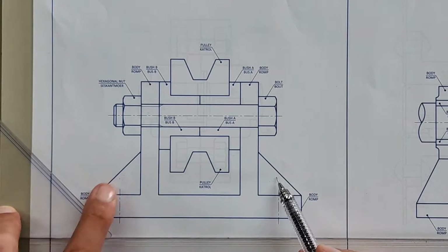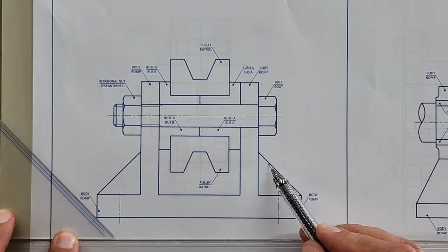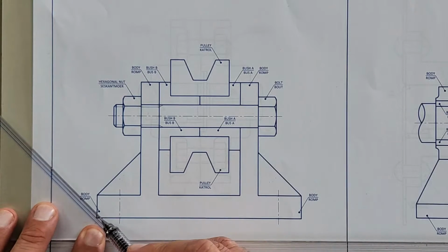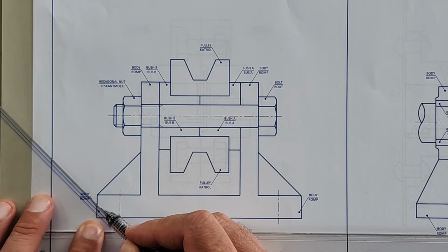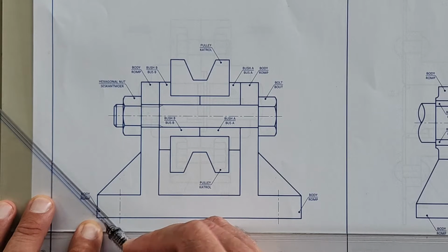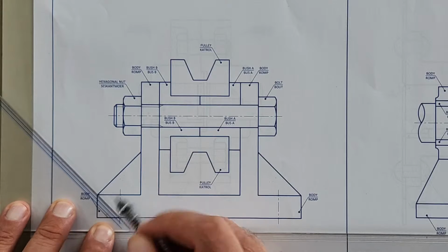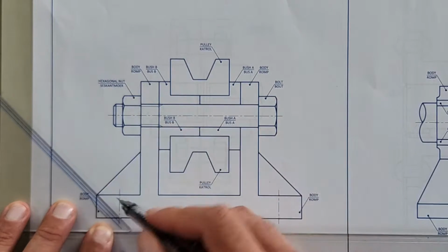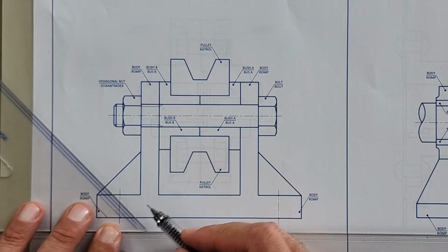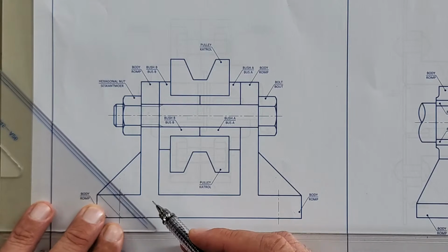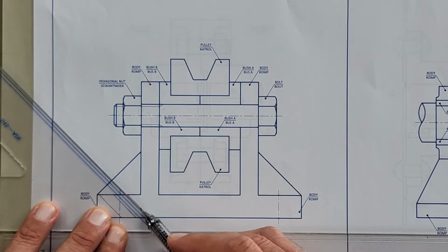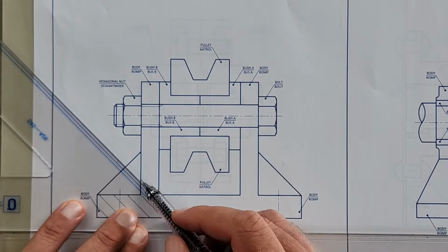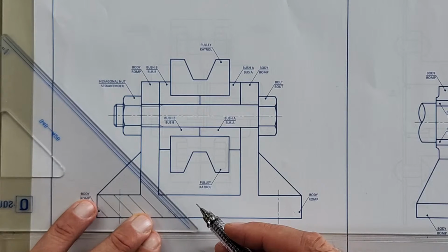Alright. The ribs here on either side is there to support this body, and so if I hatch in its length like here, we're not going to hatch that. So I'm going to start off with my 45 degrees, line it up, and if you have a triangle like I do here that's got some lines for you already, you're going to use that to space, and because this is the biggest object, your spacing can be bigger than with your smaller parts. I've got a little mark there on my square, and I'm going to use that to equally space at 45 degrees all the way through this body, my hatching.